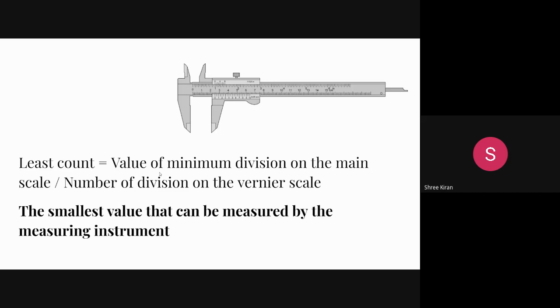Now, in most thermometers, what is calibration? A thermometer is calibrated by measuring a series of temperature fixed points: freezing points, melting points, triple points, or vapor pressure points of pure metals. By this method, we insert the thermometer in a fixed point cell, which provides the desired temperature. So we can calibrate a thermometer. These are the examples.